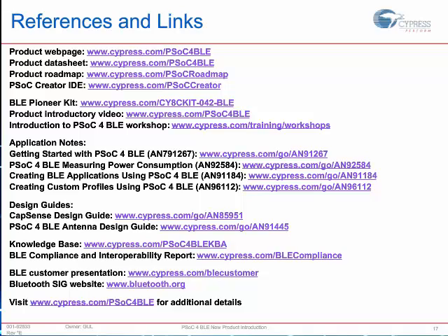So the advertising timing settings, what we call in the BLE stack the advertising parameters, are configurable within certain limits as defined by the Bluetooth Low Energy spec. You could have a device that's advertising as fast as every 8 milliseconds, which I believe is the low end of the spec. Something like a beacon or a broadcaster would probably want to do that. It's always advertising. But you can also turn that advertising down to very slow rates, as slow as once every 4 seconds.